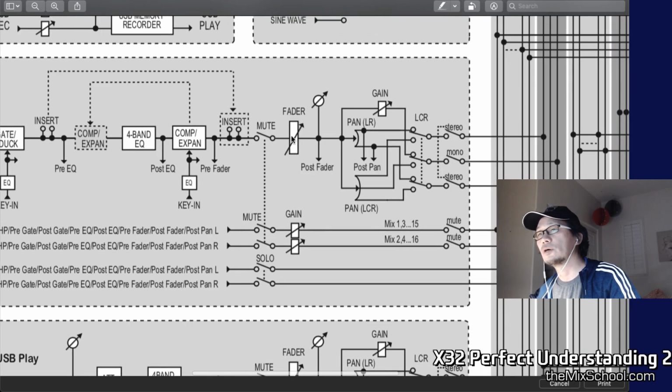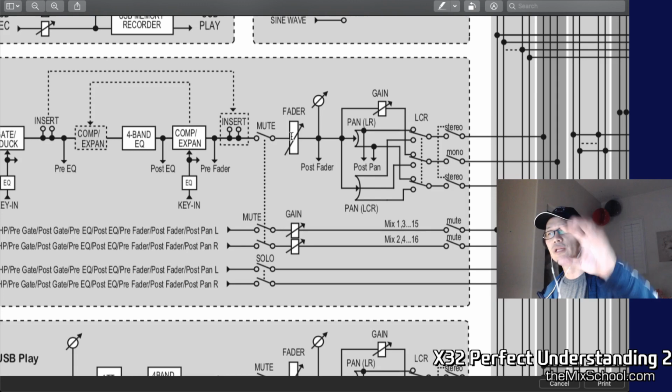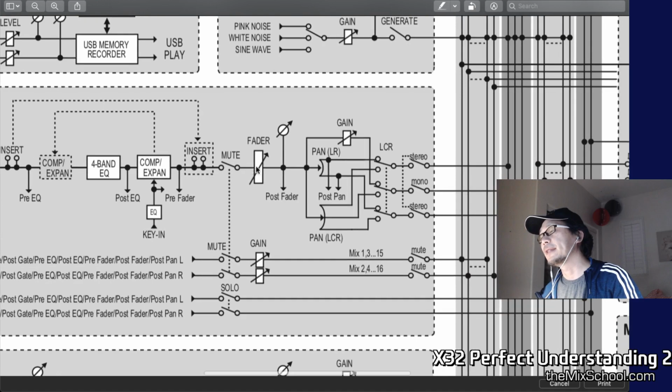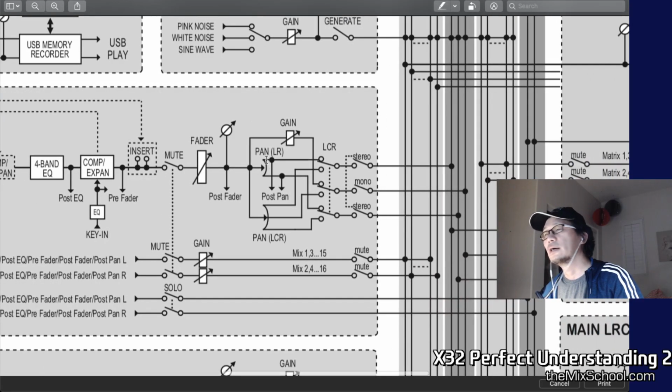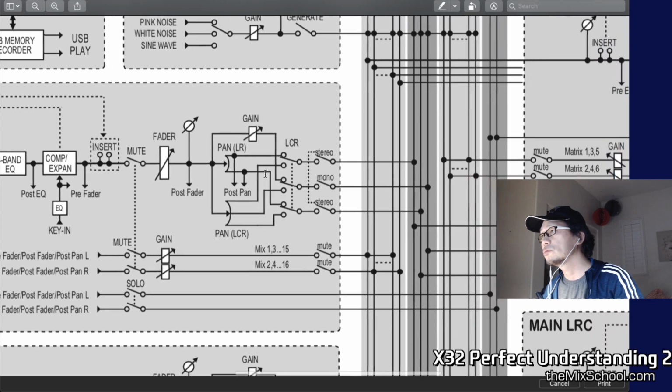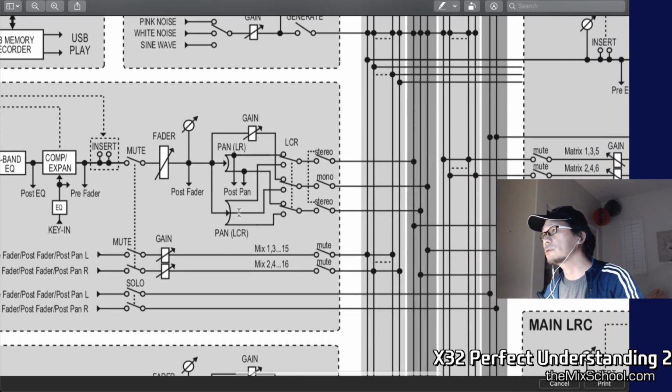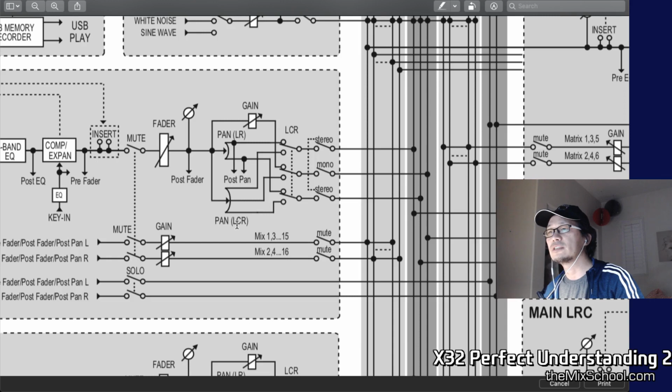And the fader here, or the level. Fader is output side. Okay, so always think, fader controls the output, the channel output, not input. Input is on input, we use gain, the trim, okay? And there's a pan, so there's left and right and mono. Okay, mono is the extra out, but when you use LCR 3 channels mode, then you can select center, left and right here.